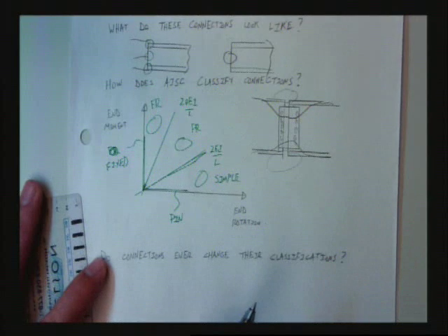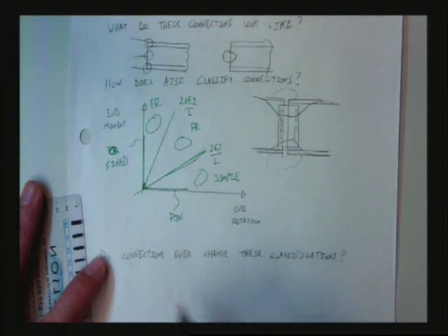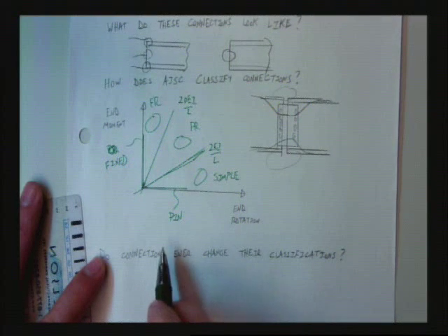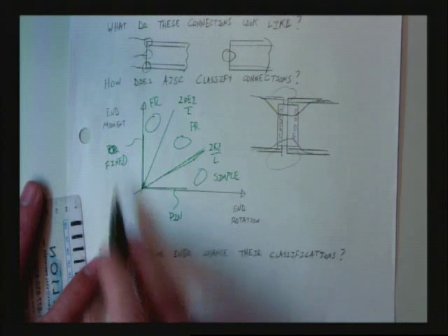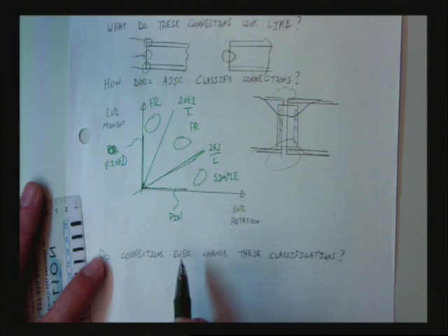And remember, if we're dealing with prismatic members, what does prismatic mean? Has something to do with prisms. Right? What's prismatic mean? Who knows? It's got the same cross-section. Very good. Thank you. It's got the same cross-section throughout. So if you have the same cross-section throughout, it is always conservative to assume a lower amount of stiffness. If you do not, it is not always conservative to assume the same cross-section throughout.